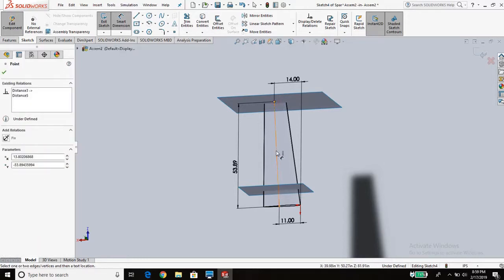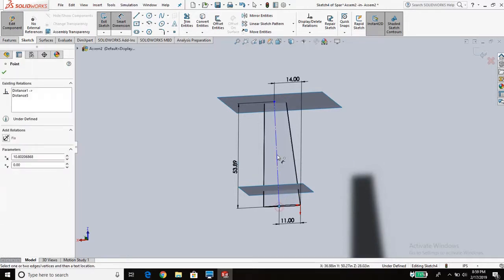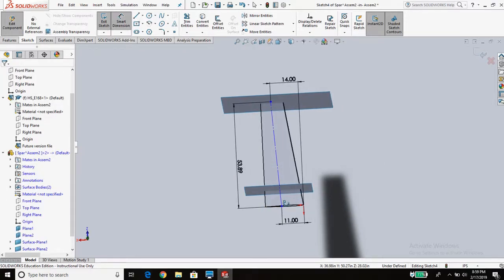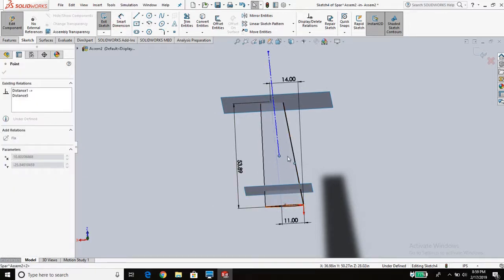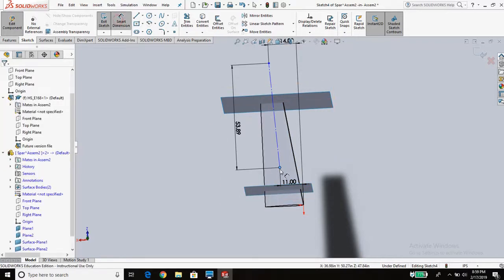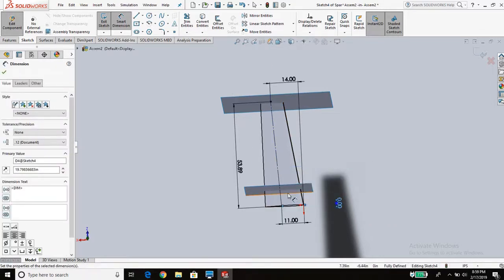One thing you can do to check is just try to drag this thing. As it drags, that's how you know where the dimension is wrong. Well, you gotta get out of smart dimension. Okay, so clearly it's unconstrained somewhere, and it's that Y component. So if we make this dimension here 0, okay, now it's fully constrained. This line is now black.